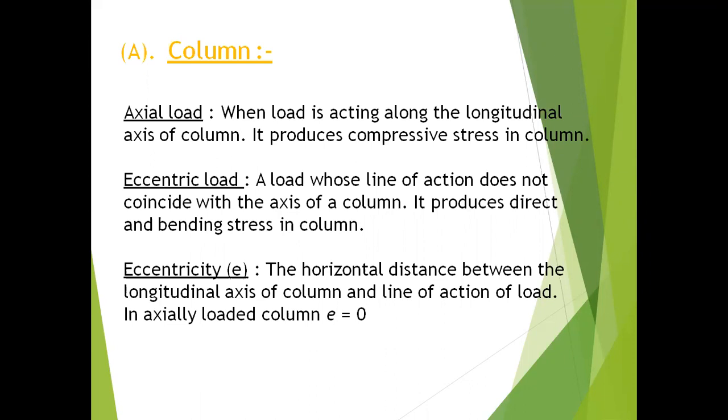So like this, in the whole structure, how many columns will be there? Every column should have an axial load alone to make only a direct force in the column. Will it be possible? So practically it is impossible. That is the reason why this is the biggest challenge for engineers, to make axial load alone transfer in the column. Anduvalla, what happens? It is not possible. Then what happens when it is not transferring only an axial load? Ante, there is some eccentricity taking place.